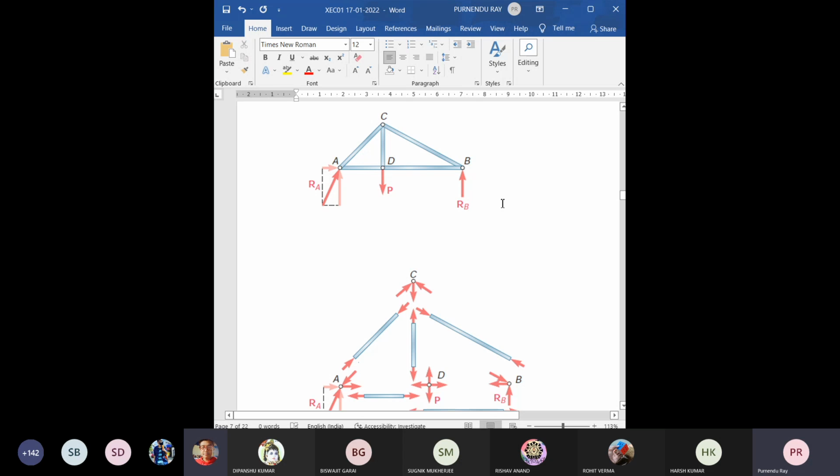It may be a purely graphical solution, where you draw the lines according to their magnitudes. So length must be proportional to the magnitude with a suitable scale. There it should be purely graphical, meaning you have to measure the resultant length or unknown straight lines, measure the length and multiply with the scale factor. You get approximate values, maybe 5-10% off due to error in drawing or measuring the length, etc. It might be something hybrid.